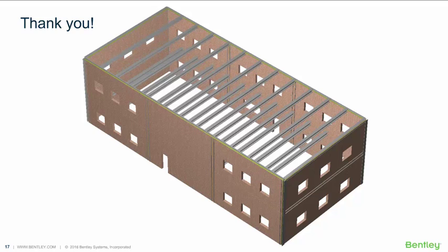There's one that was asked earlier, Francisco, that we promised we'd get back to: can you model a masonry infill panel between the steel framing to take lateral loads only? Without seeing a sketch of the configuration, I would say that we have two types of members in the structural system: those that resist only gravity loads, and those that resist both gravity and lateral loads. We don't have an element that resists only lateral loads.